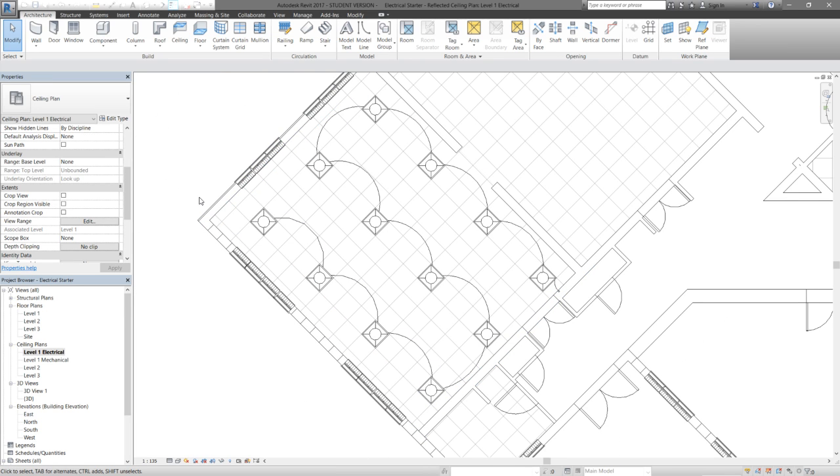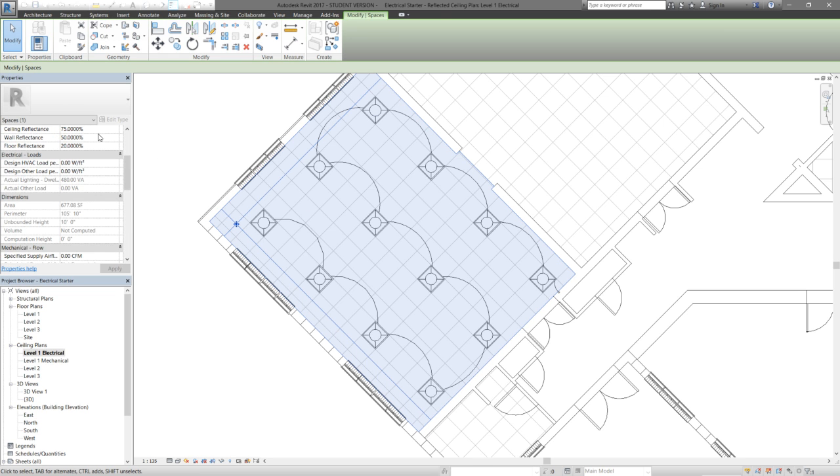Now, depending on how big the room is going to decide how many lights you're going to need. We're going to place a thing called a space, and that's what I have highlighted right here. So if I click on that, in our properties menu here, we have different settings. The important one that we're going to want is our average estimated illuminance, which is shown right here. And that value changes with the amount of lights you have in the room.